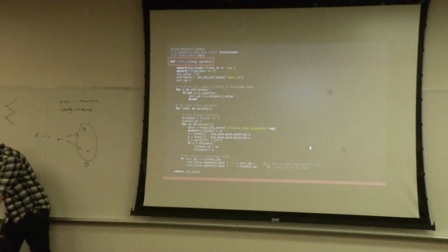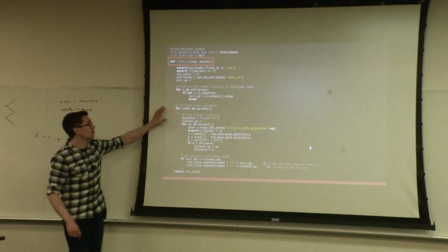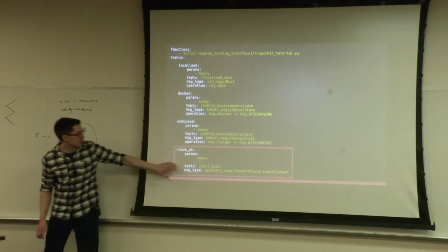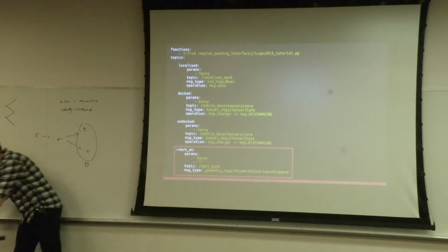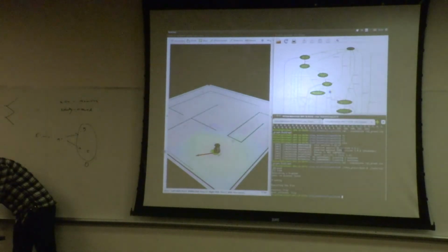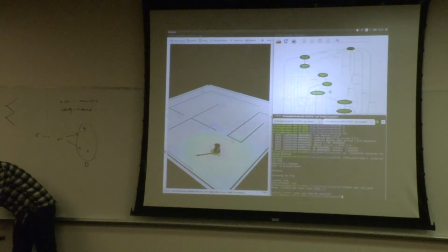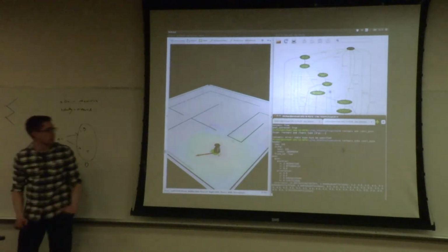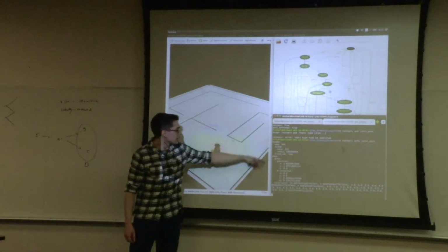it's using this function. So the AMCL topic is here, and actually AMCL pose, I can just show you what that looks like by going to here, rostopic echo AMCL pose. Yeah, there we go. Not pub, sorry, echo. I always do that. Okay, so this has published one message so far.